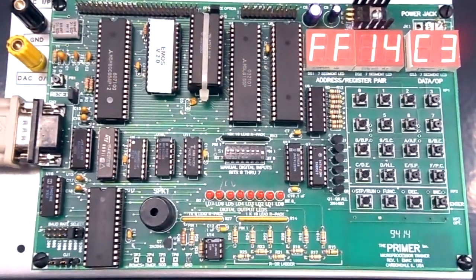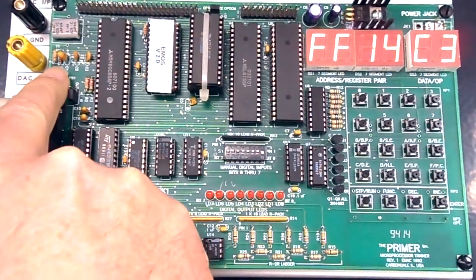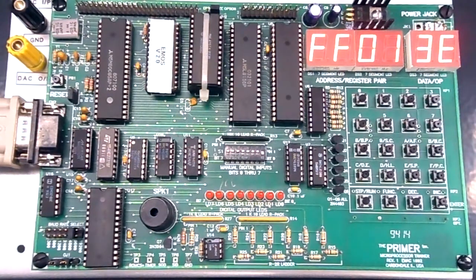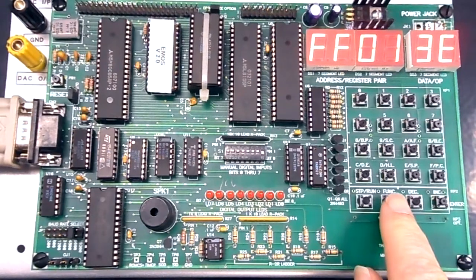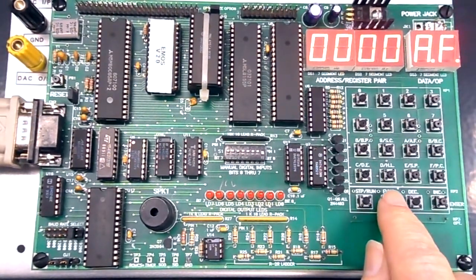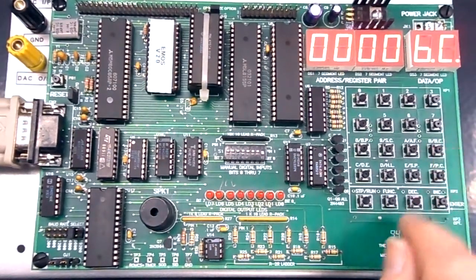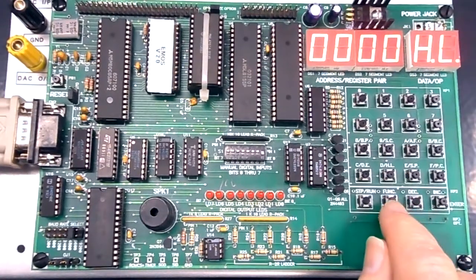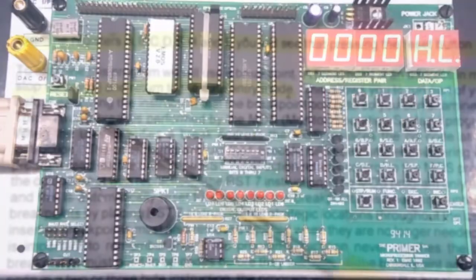So once you've entered your program, they want you to press the reset key. They say that takes you back to FF01. And it says, if you examine the registers, you will see that pressing the reset button clears them to 0. So I'm going to check my registers. I'm going to go to function AF registers. They are 0. Function BC, function DE, function HL. You can see that they've all been reset to 0, 0.